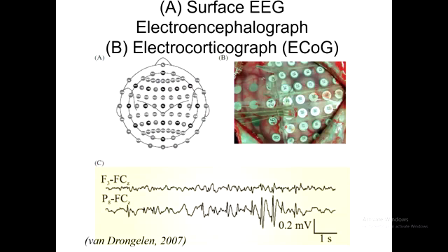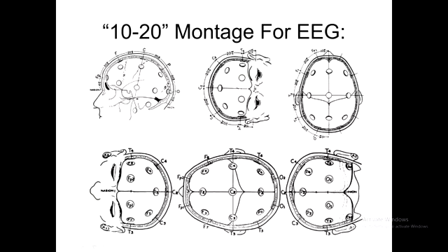As you appreciate, EEG signals are several orders of magnitude lower than ECG or EMG signals, so to get around the volume conduction problem from where the action is of the signal to the surface, as we encounter more resistance, quite often it's appropriate to take the scalp, remove the top of the skull and put in electrodes directly on the surface of the brain. And here's a group of electrodes placed like that.